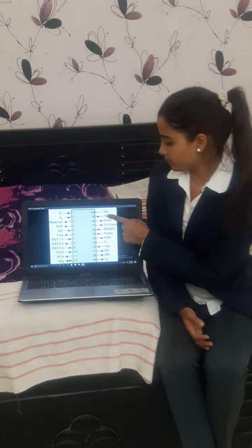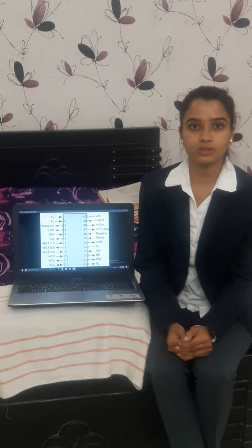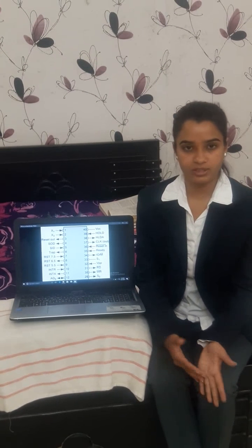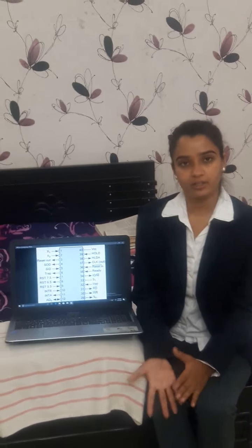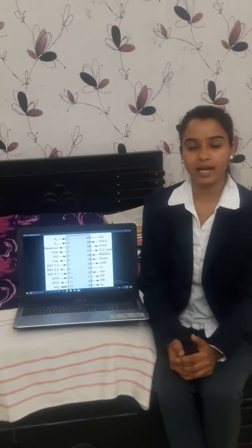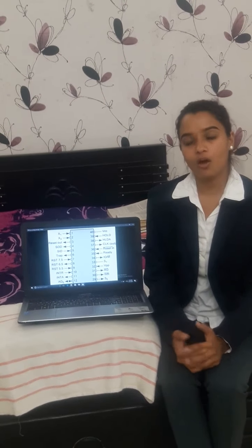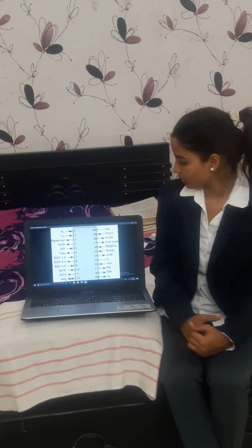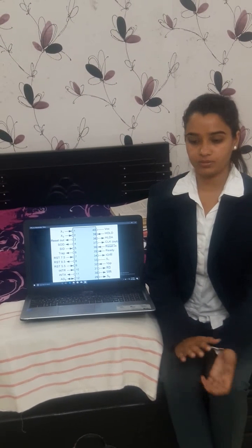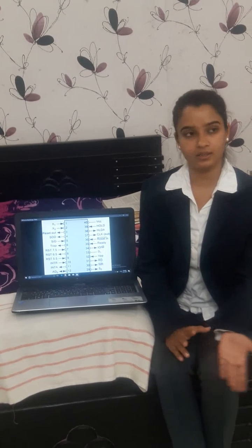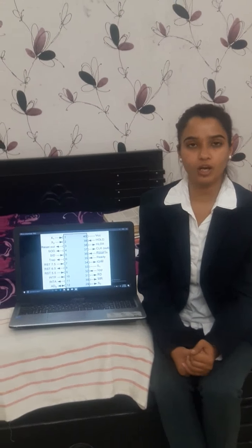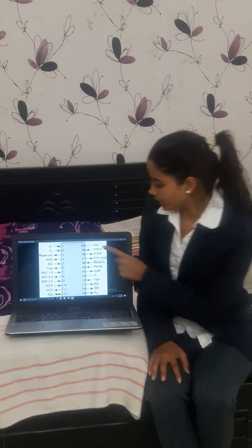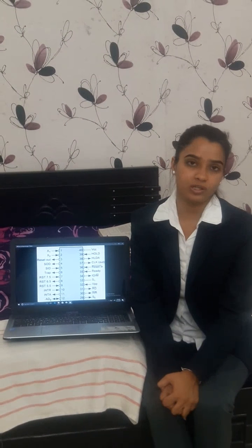the DMA is requesting the processor to give up control over the system bus. With HLDA, the CPU microprocessor has acknowledged the hold request of the DMA and gives up control over the system bus for the DMA controller to take over and operate it according to itself. In this way, the CPU remains idle and data transfer between the input output and the memory is done without the interference of the CPU. The last pin is the VCC pin, which is the voltage pin.